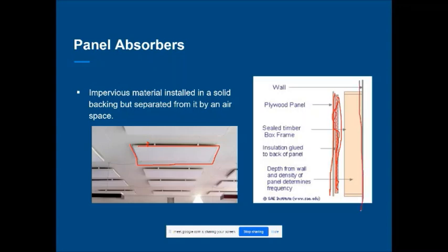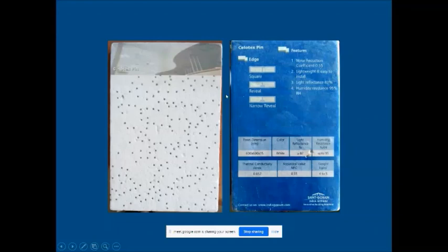And this is the wall. This is again gypsum board, and you can see it has small porosity, small holes, right? Due to this it will act as a sound absorber. If you see in detail, the noise reduction coefficient is 0.55, lightweight and easy to install. We can have a square edge, or a reveal edge, or various types of jointing, with various edges.